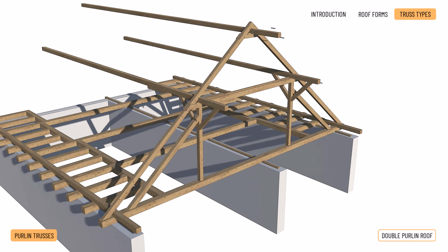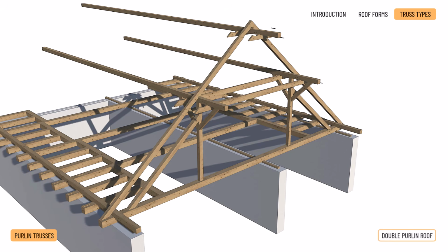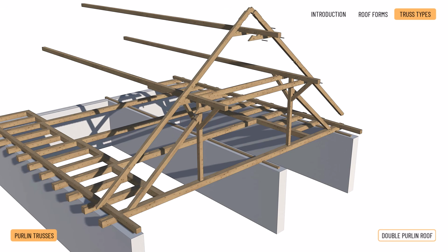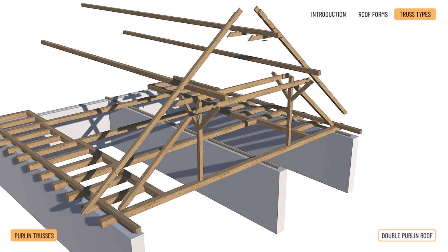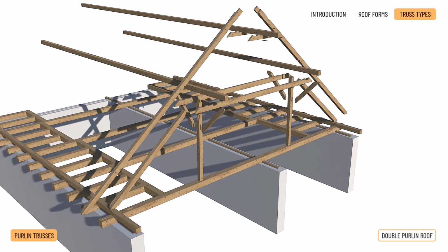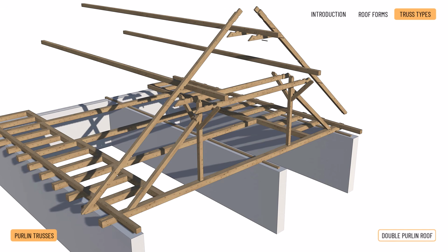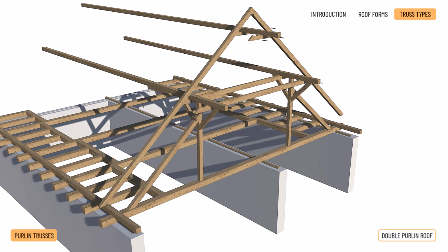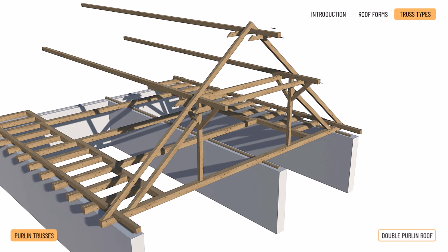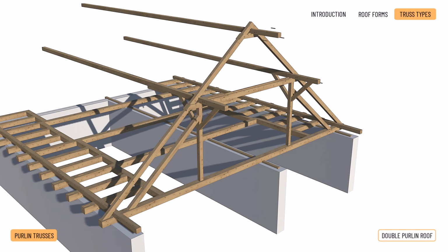Typical joint types are as follows. Rafter ties and collar ties are connected to the rafters using dovetail lap joints, reinforced by stud bolts. The rafter ties connect to the posts and the purlin using simple notched joints. Similarly, the ridge beam and the collar ties are joined by simple notches. The struts connect to both the posts and the tie beams with sailed mortised housing joints. The posts connect to the tie beams and the purlins with straight tenons. Knee braces join the posts and the purlin through mortised housing tenons. Finally, the rafters are supported by the purlins with simple bird's mouth joints.